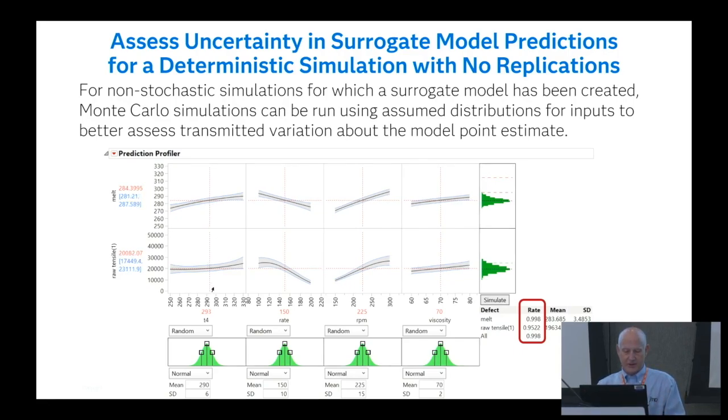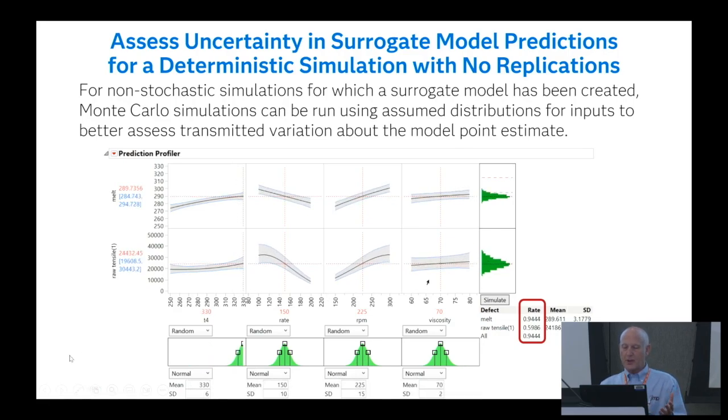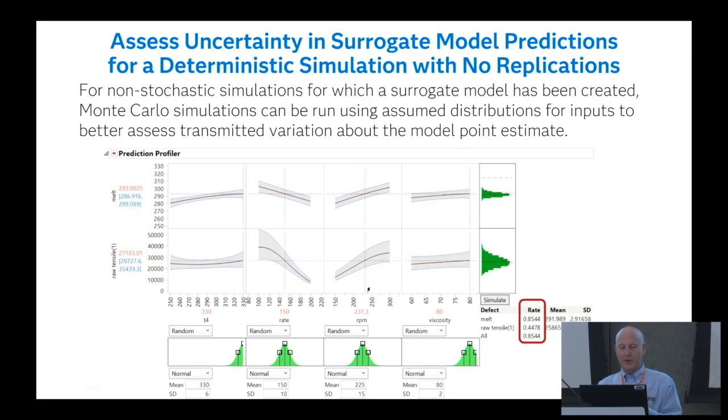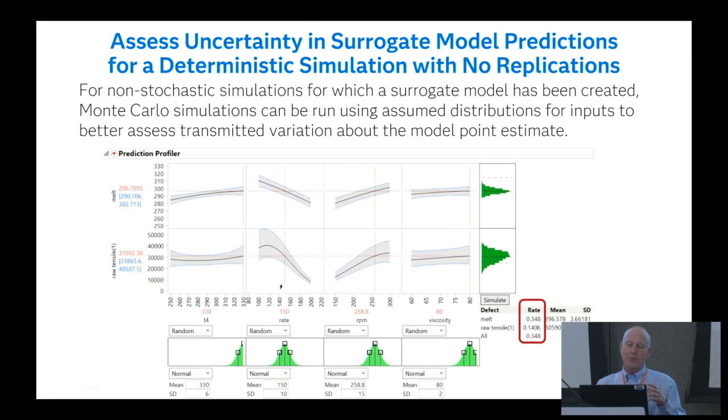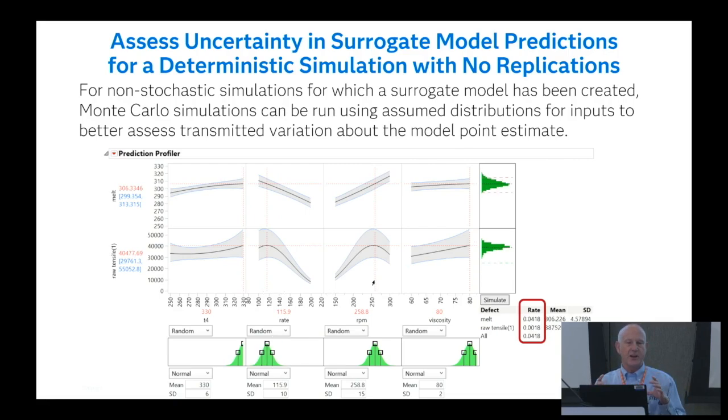So I'm just going to turn on this animation here. And as I move the process, you can see that the defect rates are going to begin to drop as I move the process into the spec limits. But at some point, I'm not going to be able to ever get the top distribution other than it being centered within the spec limits. There's always going to be some leakage of the tails outside of it. I'm always going to have a certain amount of defect rate there. The bottom distribution is sufficiently above that I'm really in the clear there.